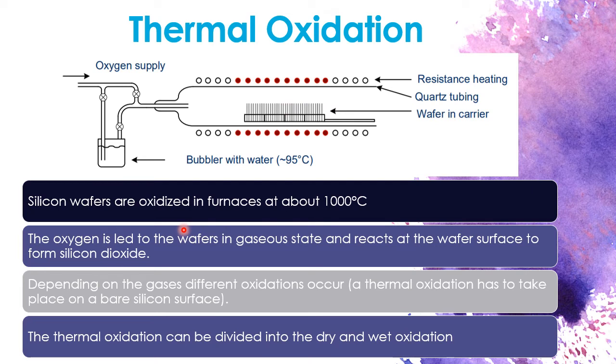In order to avoid cracking or warping, the quartz tube is heated slowly, at around 10 degrees Celsius per minute. The tempering of the tube can be done very accurately via individual heating zones, because there are several heating zones in the quartz tubing.